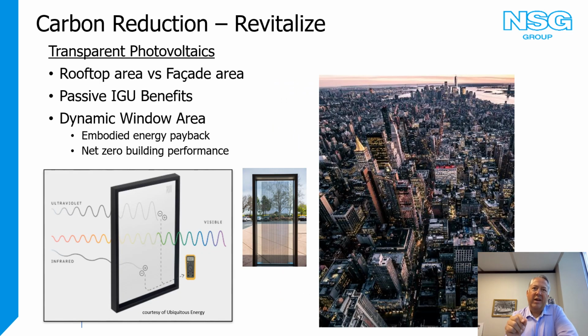And we're working on a number of ways to help revitalize the types of technology and glazing that get put in. So this is in things like using transparent photovoltaics in the visible areas, building integrated photovoltaics where your window becomes a solar generator. These could be in things like dynamic glazing and electrochromics and other materials, but there are a number of new technologies that can also be implemented that help this overall performance, carbon, and energy efficiency metric on-site power generation. So we're trying to work with a number of different technologies in this space as well.